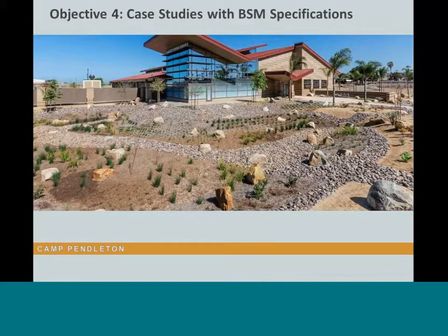And Camp Pendleton, there was a photo of this earlier, so this is a pretty large bioretention basin. I like this just because I think the landscape architect did a really good job making this blend in with the overall aesthetics. So it looks pretty good, and it's very functional. A lot of storage volume. This requirement was actually a 95th percentile storm event because it was on federal property. They have their own LID manual that requires that.